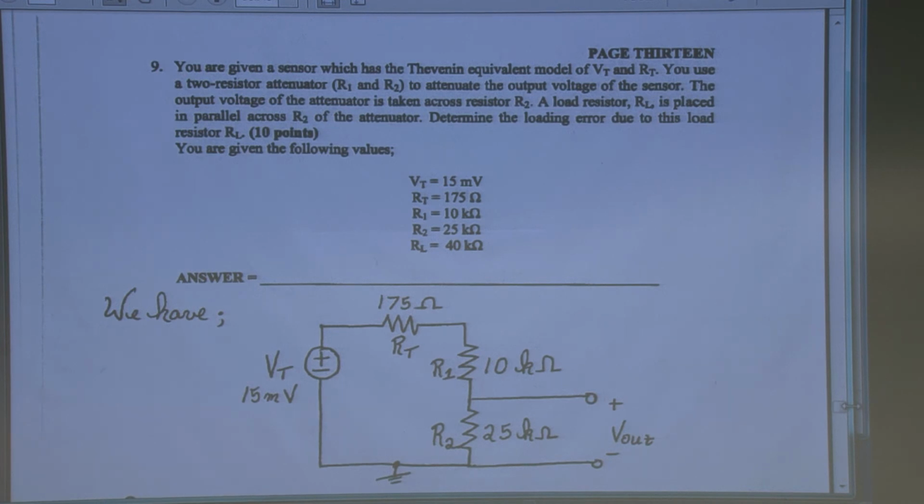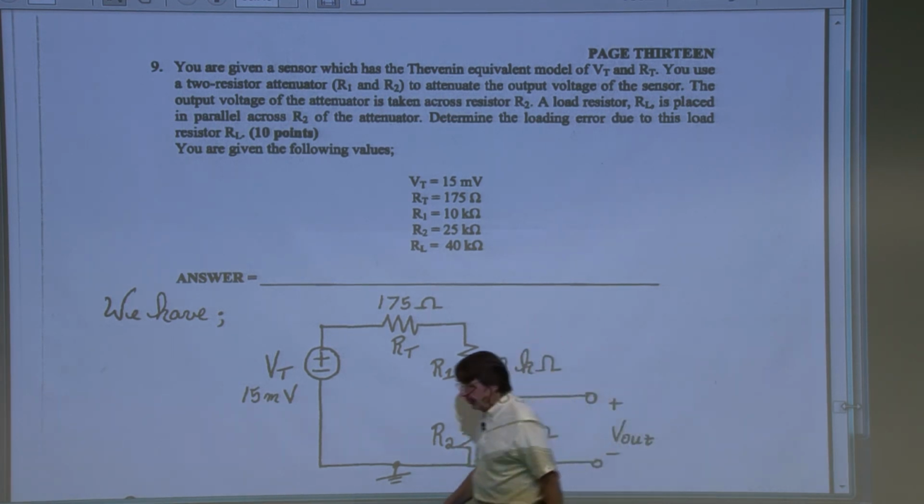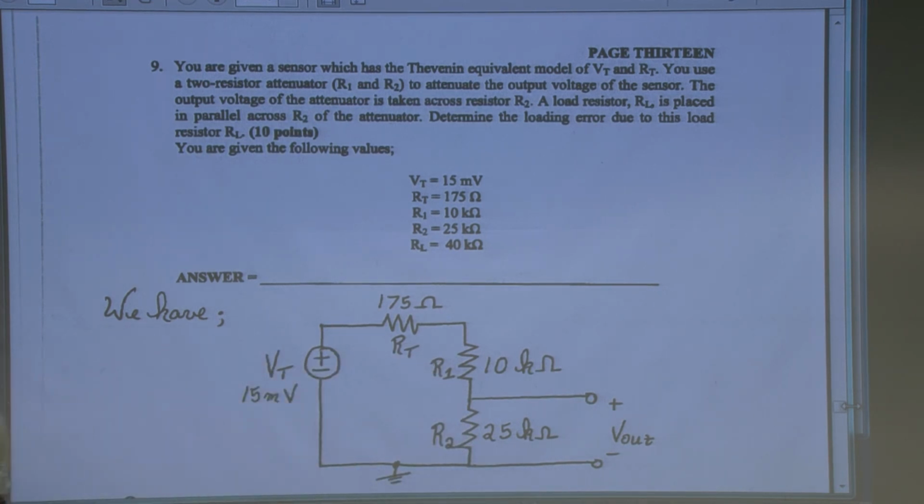My colleagues, just to wrap up, I'm going to measure this voltage without the load. Then I add the load, and I measure the voltage. The second reading will be lower than the first if you've done it right. Take the difference. That's the loading error. And I give you all the numbers. A wonderful tool to use